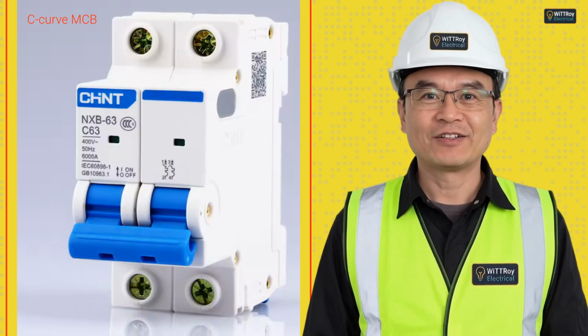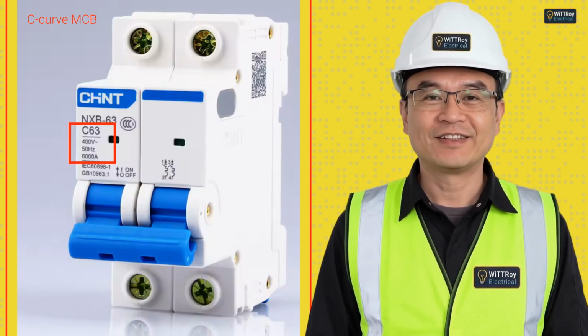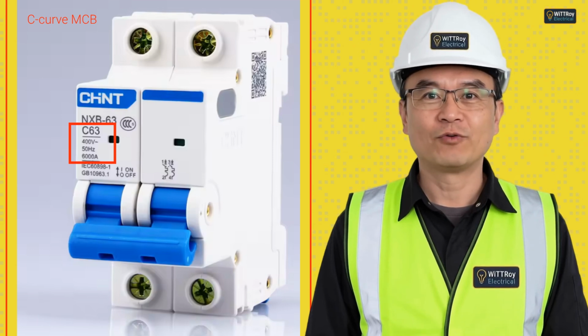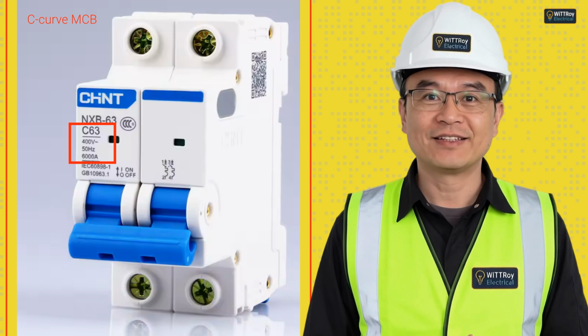Let's look at this device. First, I check the label. I can see C63. That means it is a C-curve 63 amp device. This is a C-curve MCB. I can see 400 volt AC and 50 Hertz. This means it is rated for 400 volt AC, 50 Hertz.